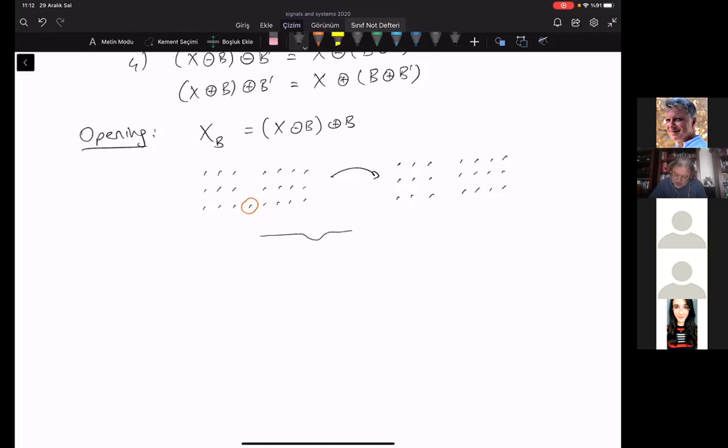But there is a place like this where this lead path becomes dangerously narrow, but it's still connected. So you want to detect this as a defect candidate, because there is a risk that, probably because of the reduced width, the resistance will be increased, the conductance will reduce also. Therefore, it will heat up from that narrow position, and after some use, maybe it will be disconnected. So if you apply opening here,